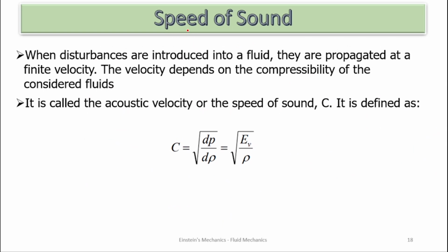Another aspect that we have to consider for a fluid is the speed of sound. How best sound can travel through the fluid, be it a liquid or a gas. When disturbances are introduced into a fluid, they propagate in the form of waves at a finite velocity. The velocity depends on the compressibility. That means we can also say the speed of sound, since it depends on the compressibility, also depends on the elasticity